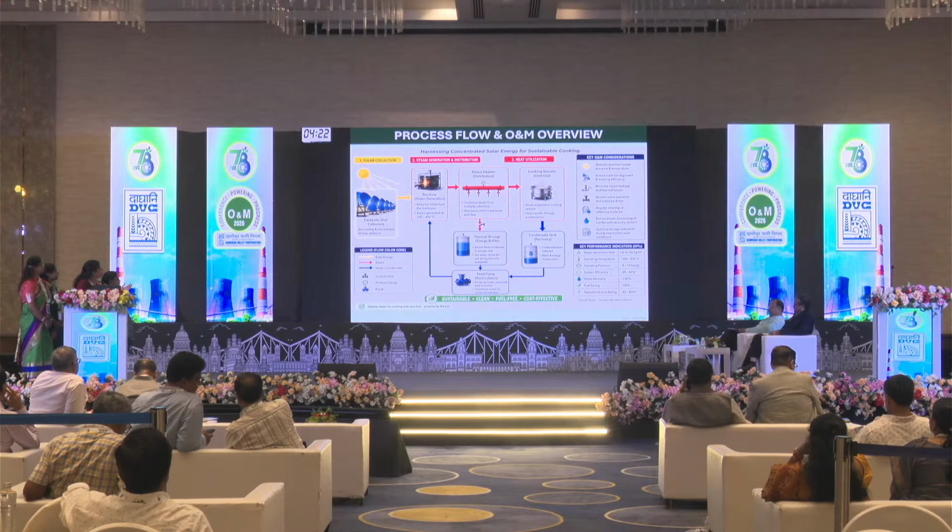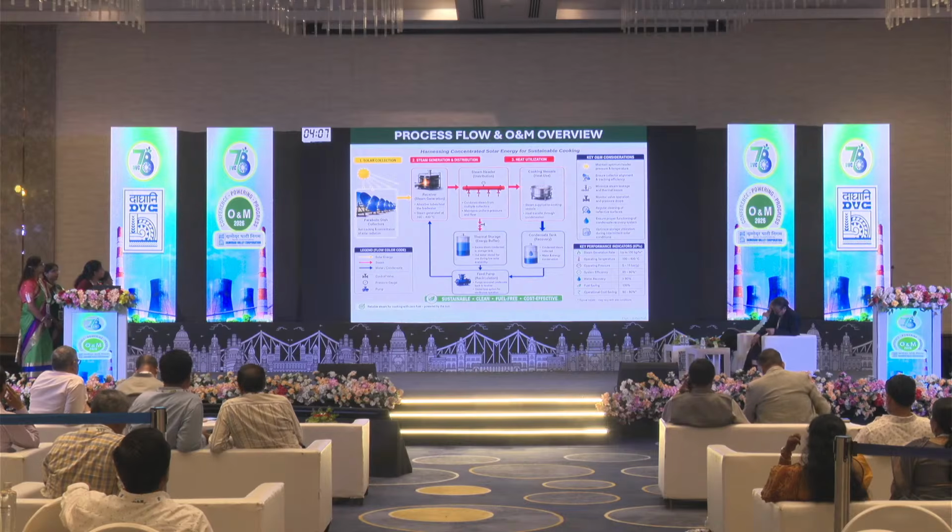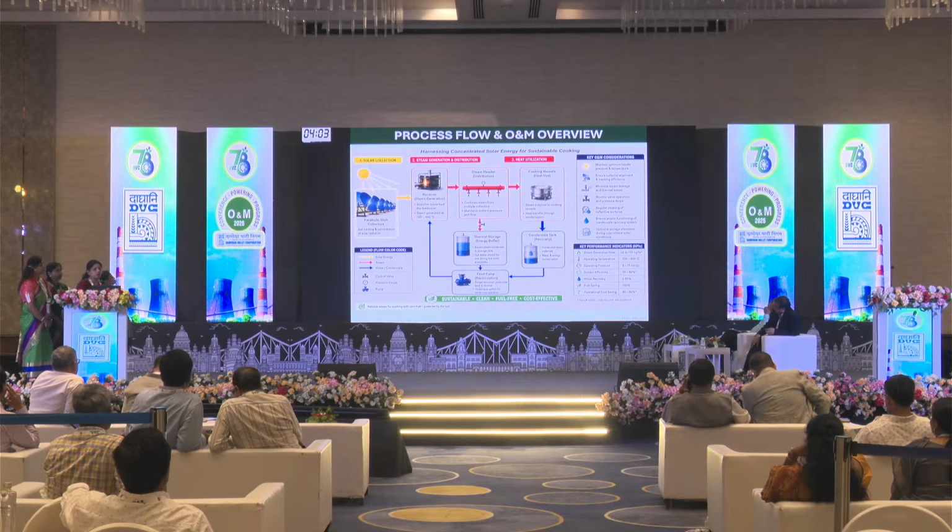Now, the steam transfers energy to the cooking vessels via condensation, and this condensate is then collected into a condensate tank, thereby helping us conserve water. Now, this hot condensate is then fed back into this system via a feed pump, and it effectively makes the entire system a closed loop system, helping us conserve thermal energy as well as water.